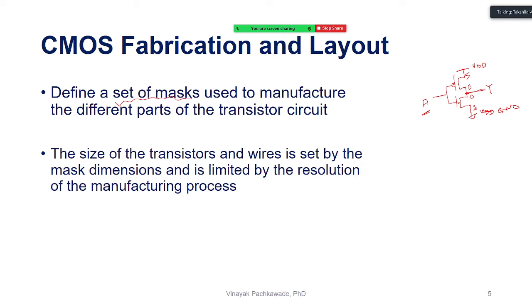So what I'm saying is that the transistor size is set. I'm designing this circuit using 14 nanometer technology, so I have a technology library and all that. And these are the wires. When I say the polysilicon wires, which are going to connect two gates, the dimension of that polysilicon is already defined in the library, the width, for example. You cannot have a larger width, okay? So as a PD engineer, you should know this information, which is already supplied with the library given to you, okay?